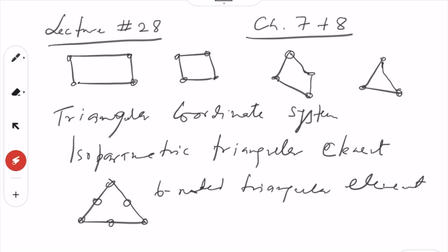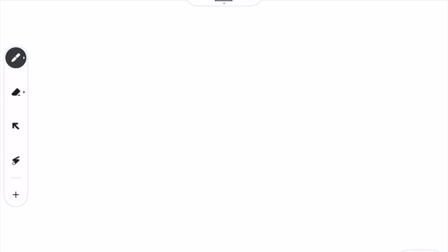So it may be easier to just use the isoparametric element, and that way it is easy to integrate among others. Second thing is you also get a different perspective, this is not the only way of finding out the stiffness matrix for a triangular element.